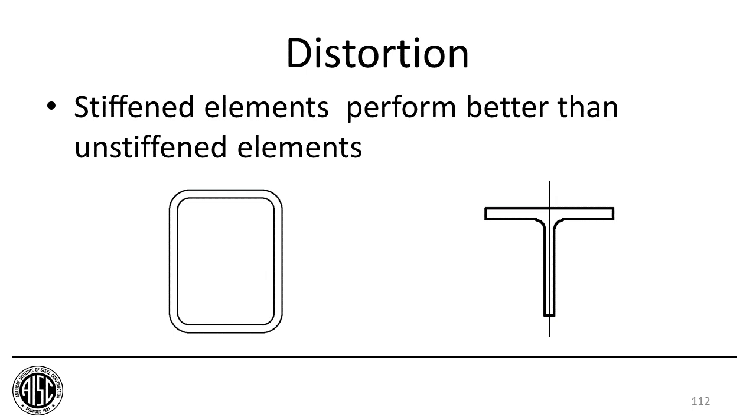Okay, yeah, your typical fabrication shop has a setup to do cambering, which is going to essentially provide a small curvature, or a large radius curve, about the strong axis of a beam. So cambering is a curvature that is intended to offset the gravity loads on a beam.